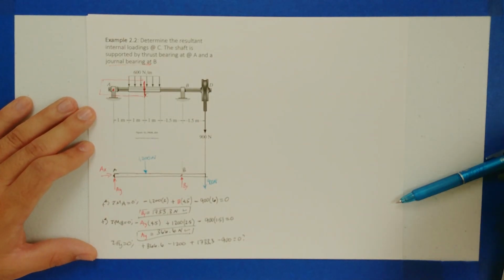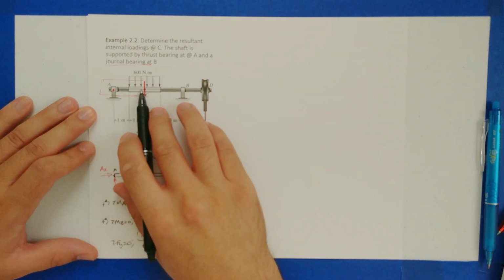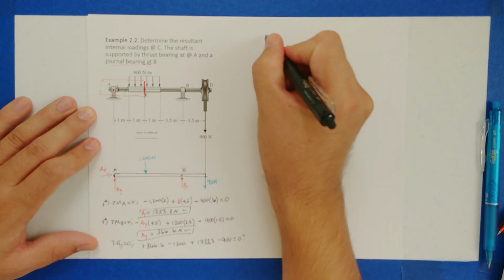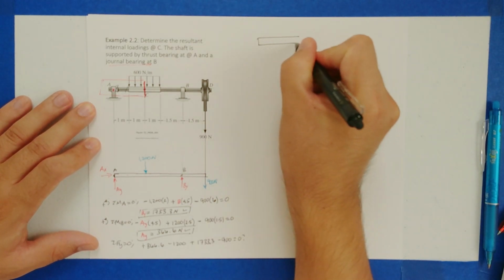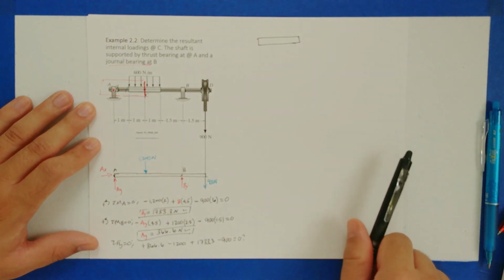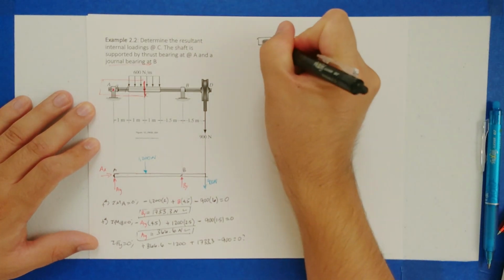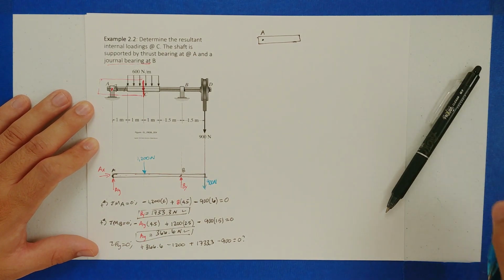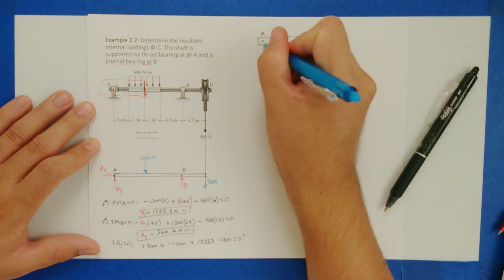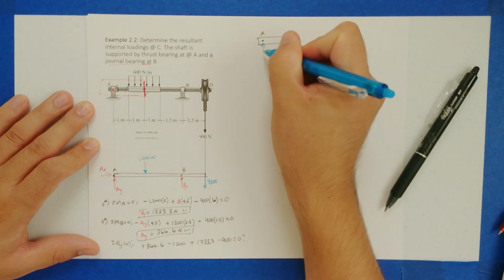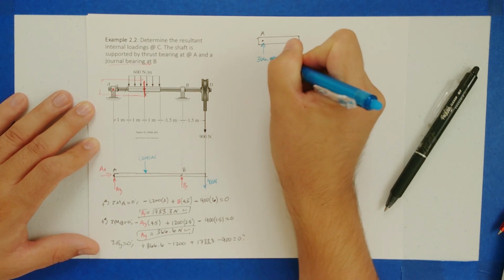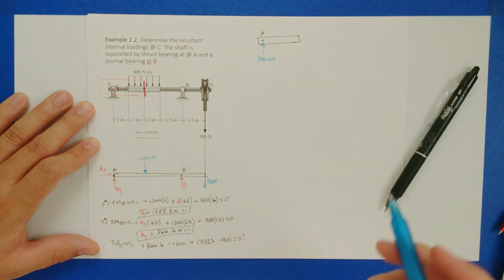I take these values. Now, I said I was going to use the left-hand section, or this one over here. So let's draw the free body diagram. It looks something like this, just a teeny little shaft over here. At point A, let's draw point A. We have a force. A, we said, was 366.6. I'm going to color it blue because I know it's known now. I'm pretty confident that that's the reaction force from that bearing.